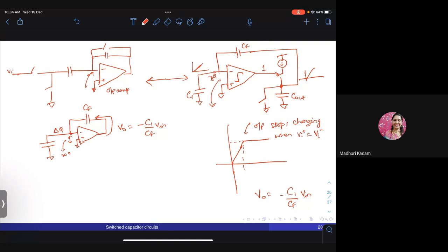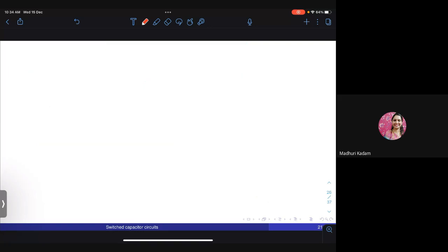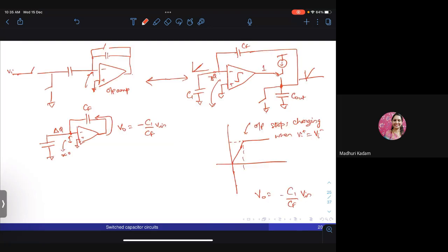Basically, this circuit is just a chain of amplifiers. With an op-amp, you have to be careful because you're going to use it in negative feedback as a linear circuit. In a comparator, you're not worried about linearity, you're not worried about stability as such, because you want the output to saturate. You can just use 3-4 amplifiers in a chain and make sure that the output reaches the highest possible value. So the linearity of this amplifier is not very important.